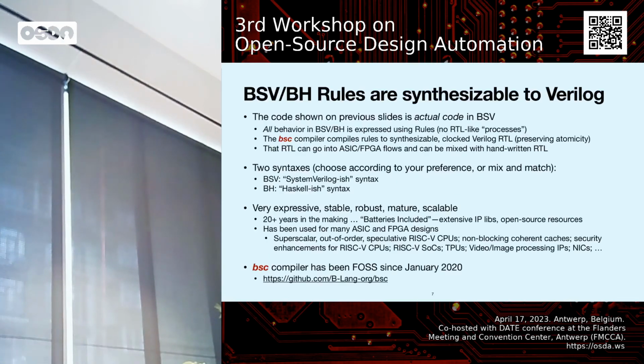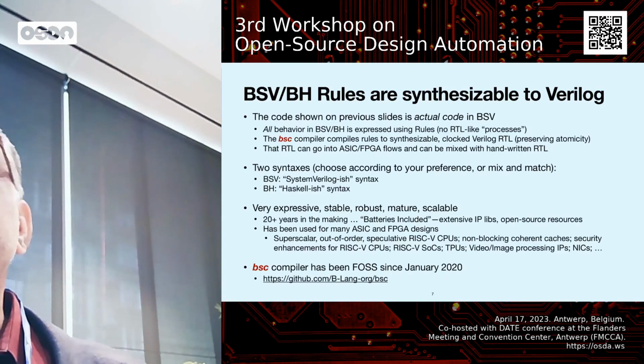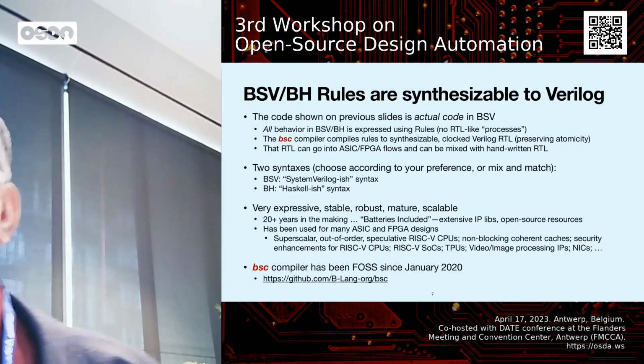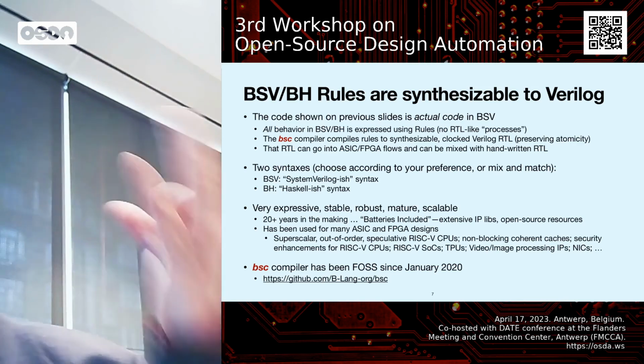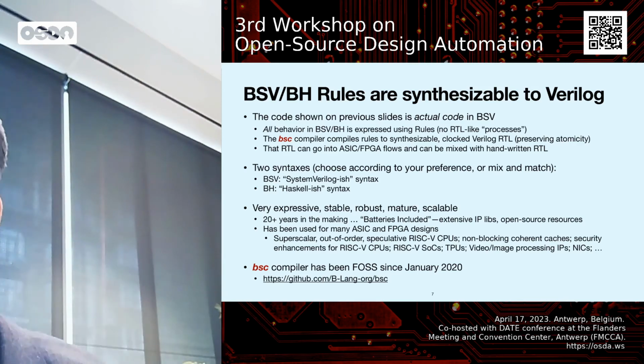But the other side of BlueSpec is that it uses essentially all the power of Haskell, including polymorphic types, polymorphic parameters, higher-order functions, etc., to make it into a very powerful language for circuit description. So if you think of generating your circuit as two phases, the static elaboration part in some sense is the circuit description part, by which you describe what's the structure of your circuit, what are the pieces, what connects to what, and how do they connect correctly from a types point of view to each other.